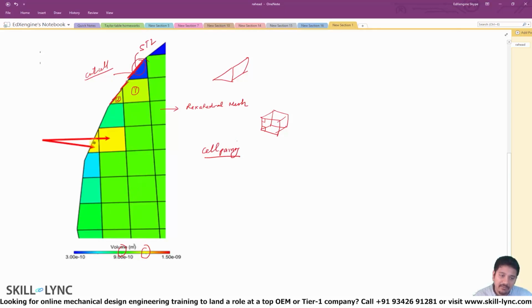So whenever you have a cut cell, for example this little triangle right here, let us just call it cell 1, and this is cell 2. So if the volume of cell 1 is less than 30% of the volume of cell 2, then these 2 cells get attached to each other. This concept is called cell pairing. Now the reason why you do this is, if your cell size is very small, because of the CFL criteria that you have, your time step is going to be extremely small, and hence you have to combine these smaller cells to form larger cells. If you don't do that, your simulation will be extremely slow.